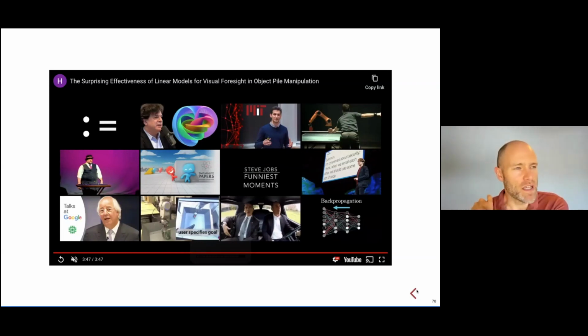First of all, the philosophical answer is that one thing that's very different about physics-based models and deep models is that physics-based models are not universal approximators. They take a stand and they say there are some conservation laws, there are some constraints, there are some things that will never happen, right? Matter will never be created or destroyed, energy will not be created or destroyed, and I think those constraints give you the structure in the problem that we often leverage, whether it's control affine or positive definite manipulator equations or inverse dynamics being sparse or whatever. And it's really decades of work finding ways to exploit that structure that has made our planning and control algorithms so powerful.